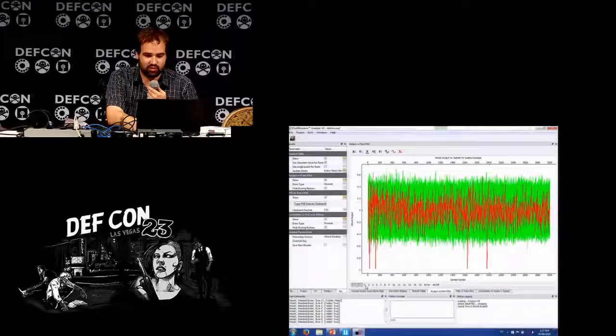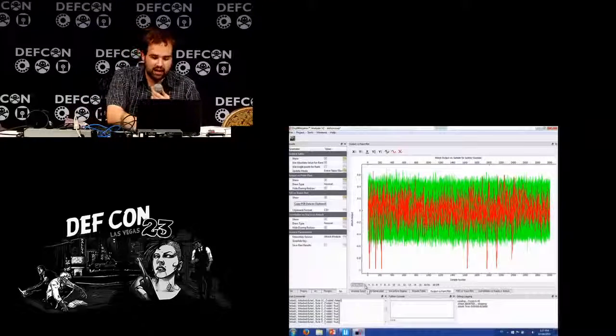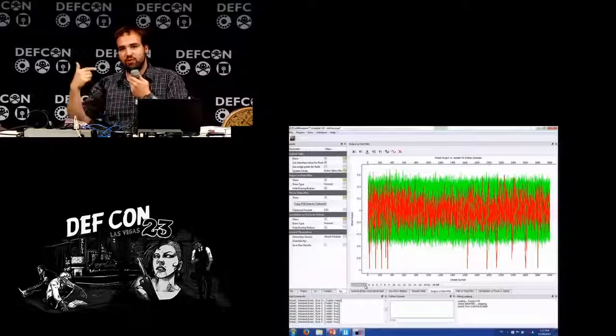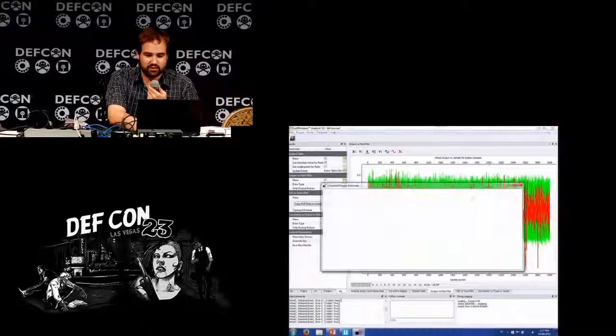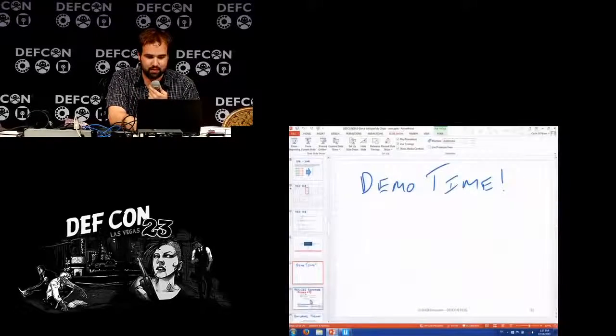And we can see that as I turn on each byte, so I'm asking it for byte 1, byte 2, byte 3, it's marching forward in time. This is because it's an 8-bit micro. There's a big for loop in there doing the key application and the SBox lookup. So that's very quickly how a side channel analysis works and how you use them against an unprotected AES implementation.